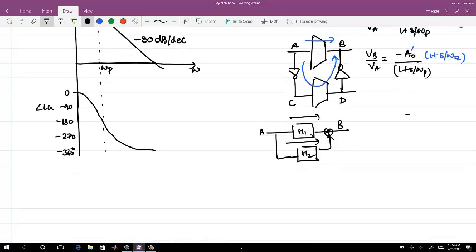Another example which I can show, I think this part you might get. Everyone would have seen from VIN to VOUT, right? And then there is a CGD sitting here. And you know that this is a right half plane zero because of the CGD. You know that, right? Or no? So now look, from VIN, because of the GM path, you are reducing this potential. But if you increase VIN, you will increase this thing due to CGD. They are opposite. And this is an example I can give.